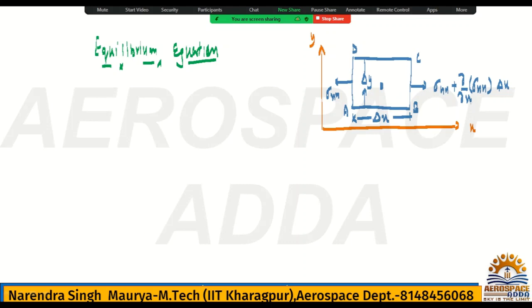So you have written this equation in terms of the length, because if you make delta x equal to 0, you will be on AD face. Make delta x equal to 0, so you will have sigma xx, which is the stress on the AD face. The same stress you will get with this equation also. But if you write delta x as some distance, say the AB length, then again you will reach the BC face. So this is the way to write the stress system with respect to the length, okay.